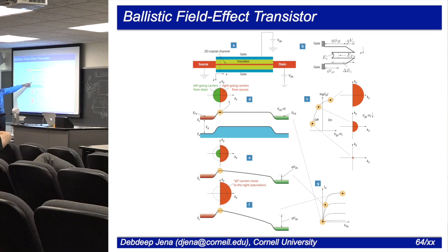At this point, these electrons in the 2D system, which are sitting in the conduction band k states, have equal and opposite left and right going states. Half of them have come from the source, they're red, right? And half of them have come from the drain, they're green. They're all like waves. The moment there's an electron here, it's a wave, so it's ballistic, right? So there's no decay. So these are in equilibrium with that.